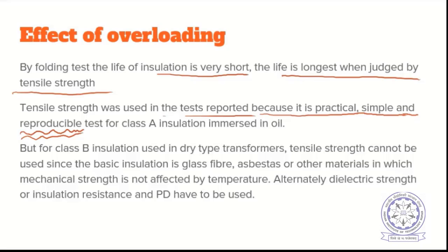If it breaks, say, after 1 year, it should break for another sample also after maybe 1 year, 1 month, or less than that, or say 11 months, something like that. They should be in the same order. That is what is required from any test. So among these tests, tensile strength was reported frequently for this reason. For class A insulation, which means paper or press board, etc., I will show you the insulation classes in the next slide. For this material, reproducible practical results can be obtained using tensile strength.